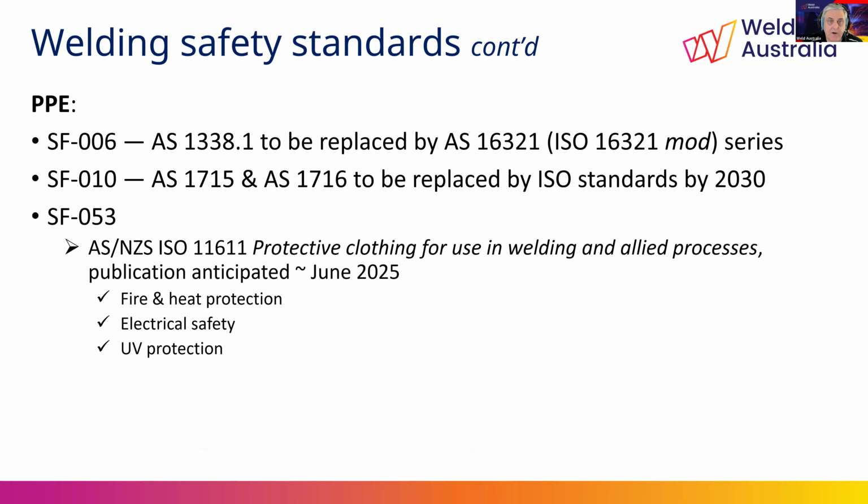Now, this year there's been a lot of activity by various committees responsible for personal protective equipment. Committee SF-006 are currently moving to replace the AS 1338 series with modified adoptions of the ISO 16321 series. Now, these standards cover welders' eye filters or protective visors.